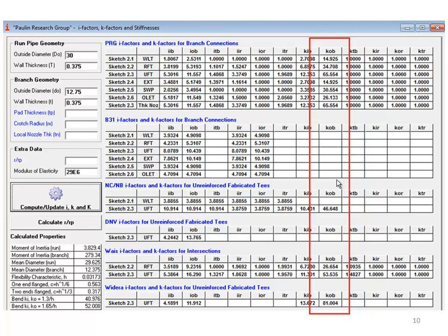Where the K factor is greater than 1, you should probably look at the configuration of the piping and decide if a K times D length of pipe concentrated at the branch will affect the results. If it will, then maybe you should use it in the calculation if load redistribution in the system is important. Where the piping configuration is not just an anchor-anchor system, when K factors are used, the displacements will likely increase and the loads will be redistributed.